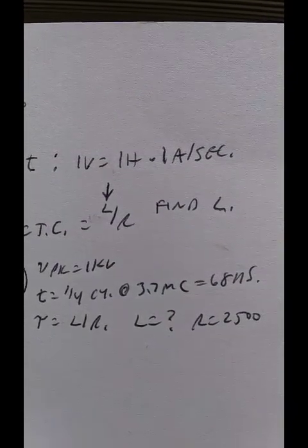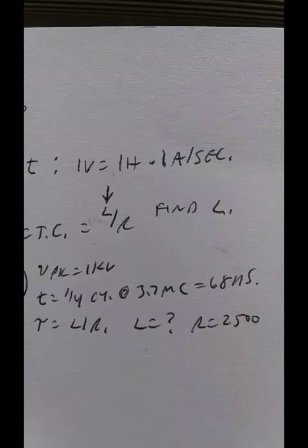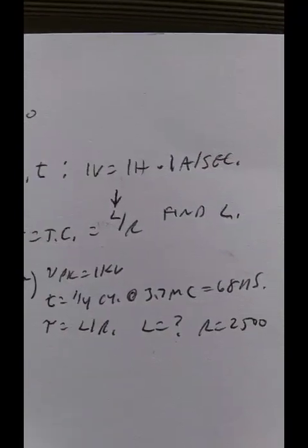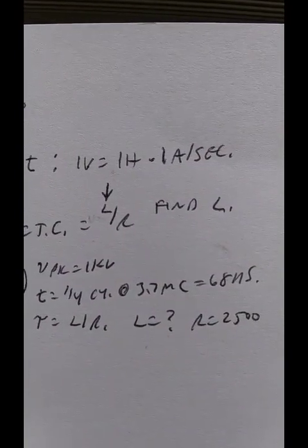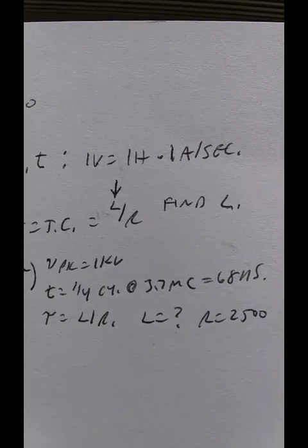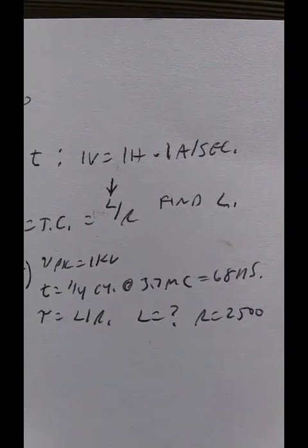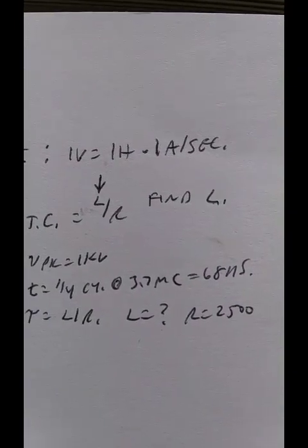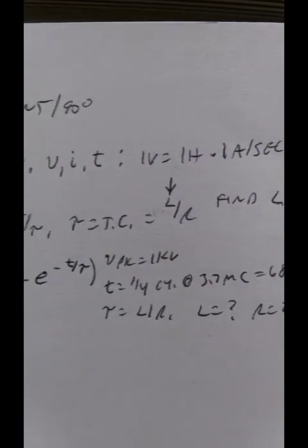Well, the basic definition of inductance is that a 1 volt inductor voltage is equal to 1 Henry times 1 ampere per second rate of current change. In the 75 meter amplifier, the current's changing at a nanosecond rate. But this is 1 second. And there's the clue as to how to crack this differential equation.